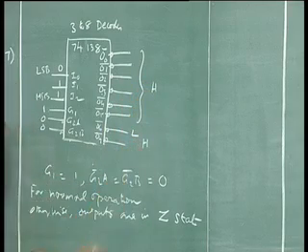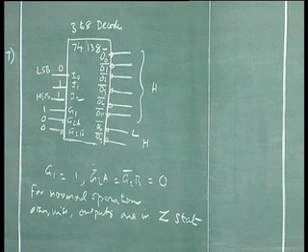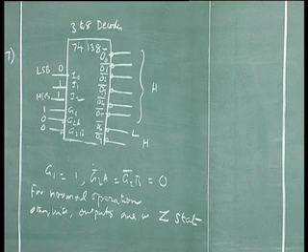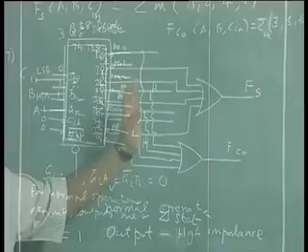Normally it will be the other way. When I say active high outputs, O6 should be high, all others should be low. In this case, this is a practical decoder, which is available with 3 enables, 3 inputs, and 8 outputs, active low. So, if I want to now use this practical decoder in my adder circuit, can I do that?